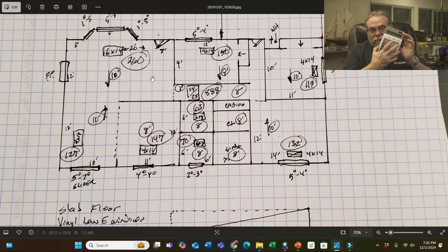So that's the leakage. She's got leakage on her return side, leakage on her supply side. That's where her leakage is all at. If we added the 179 CFM back, plus 179, we can see that she'd be right at 1200 CFM. So everything tested out like it's supposed to. We know we have leakage. We know the airflow is not so great. Was our static pressure pretty high? It was pretty high on the system, because she was using a pleated filter. So she could get better airflow. We're going to fix all that when we put the new system in, put a bigger return air in, and a better filter for her so it's not restricting the airflow.